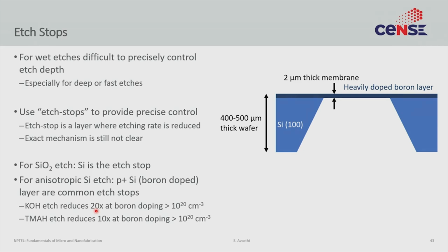There are several etch stops. This is not the only one. And often, if you are trying to do very fine etching, where you need to end with very thin membranes, it's often recommended that you use etch stops instead of just using a stopwatch and trying to time the etch.